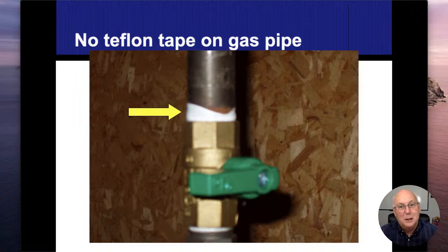So it's not always going to be brand new white or brand new yellow that you come in there. Sometimes we're going to be a little bit confused when it comes to it. But yellow Teflon tape is okay. White Teflon tape, no way. And preferred, so there's no mixture, is going to be pipe dope that comes in there.